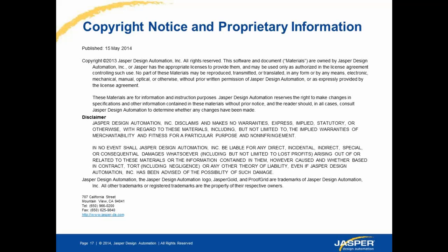Sure. Till date, you didn't have a measurement or a metric to quantify the amount of formal verification you have done so far. So using the coverage app, now you have a metric to say, this is the amount of formal verification I have done. And you can use that metric to sign off on your formal verification effort. And so if you formally verified this block, you don't need to run simulation on it.